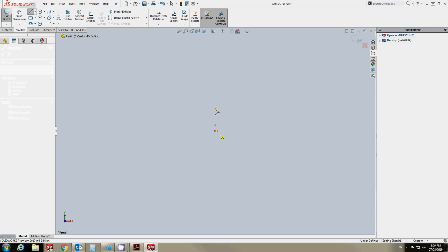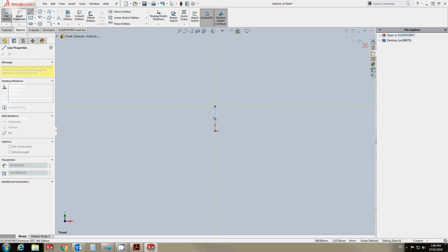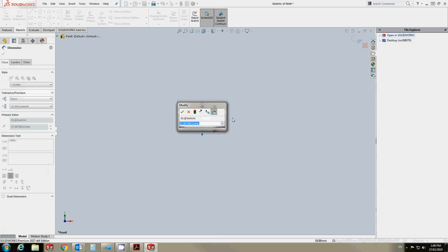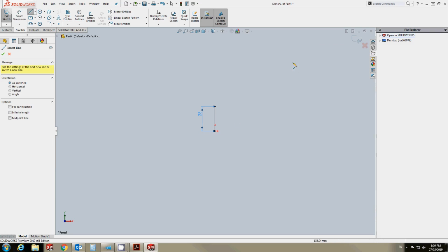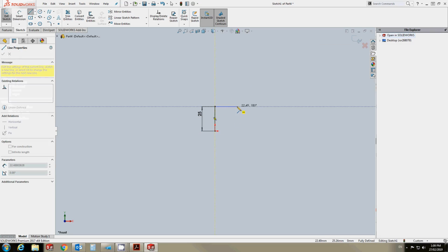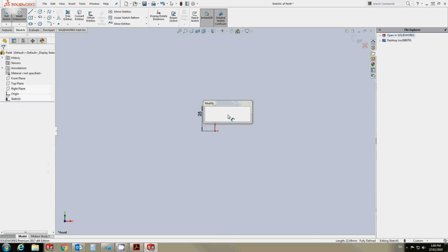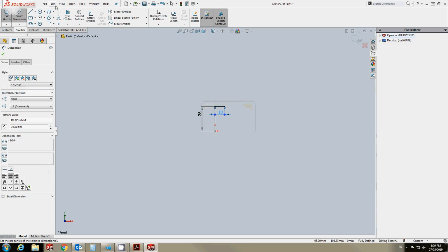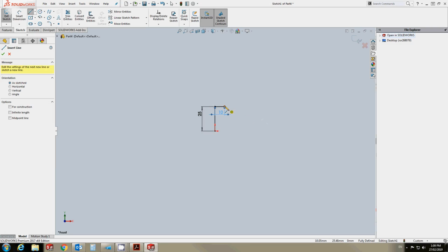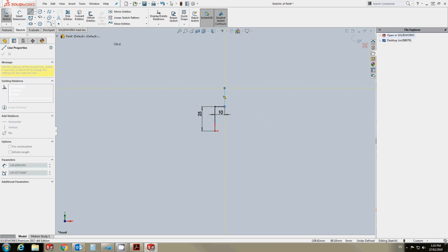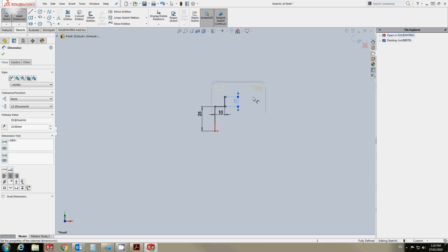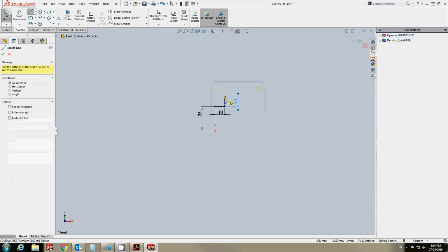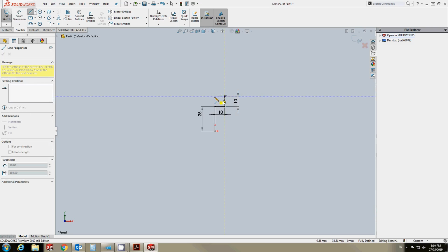So here firstly let's go up, which is 25 mil, and then turn right to 10 mil, then another 10 up, yep, and then click on here and move through here.